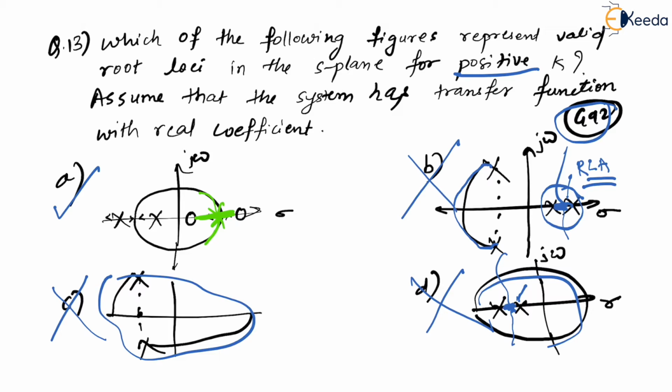So definitely, now see here again if you see this one, is it a root locus area? Yes, because you have 1, 2 and 3, you have three number of zeros and poles, right? Which means it is odd number, which means this is the root locus area. So yes, definitely there is a breakout here. There is a breakout, and since here you have two zeros, this has formed a circle here, and they are going to terminate into the zeros. So yes, option A is the correct answer.